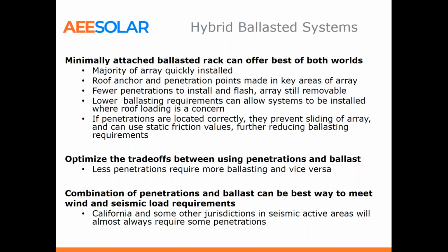So we also see we can go with mostly a ballasted racking system, but add penetrations as needed to bring the dead load, as I mentioned, to whatever is necessary. Had one building recently that had a really low dead load limit, and we went with a mostly penetrating system using Aerocompact, and we got half the penetrations that would have been needed with a fully penetrating system, but still got the array dead load down to about 2.2 PSF, which is incredible. The customer was very happy with having such a low dead load on that roof. It was a historical building that they wanted to put it on.